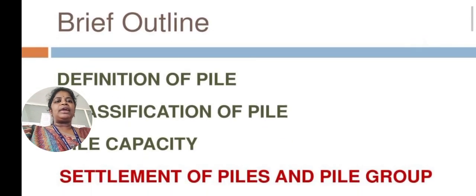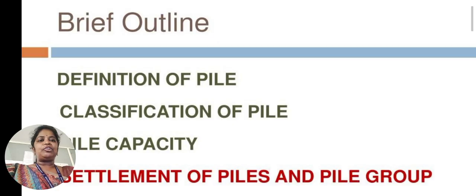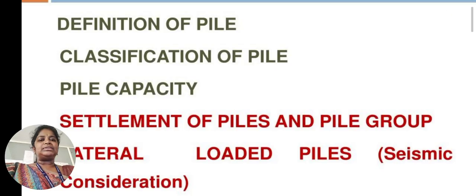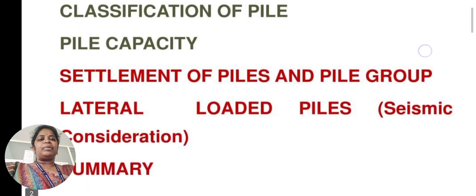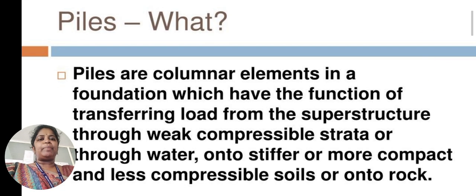Yes. Brief outline about this topic is definition of pile, classification of pile, pile capacity and settlement of pile groups, laterally loaded piles, that is seismic consideration, and summary. And coming to the piles, what is the meaning of pile? Piles are columnar elements in a foundation which have the function of transferring the load from superstructure through weak compressible strata or through water onto stiffer or more compact and less compressible soils or onto rock. That is about piles.